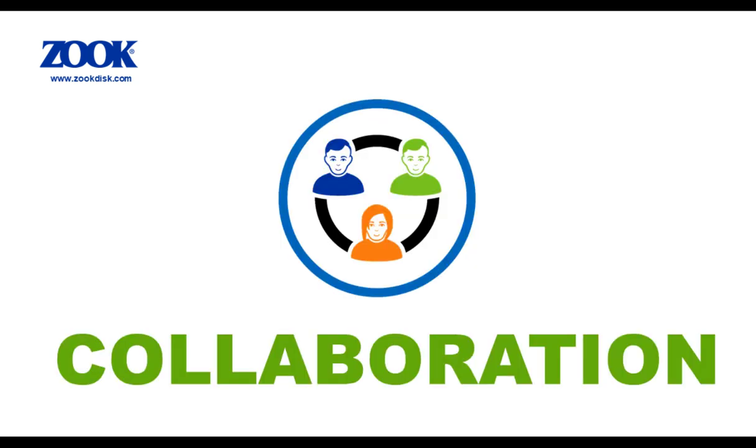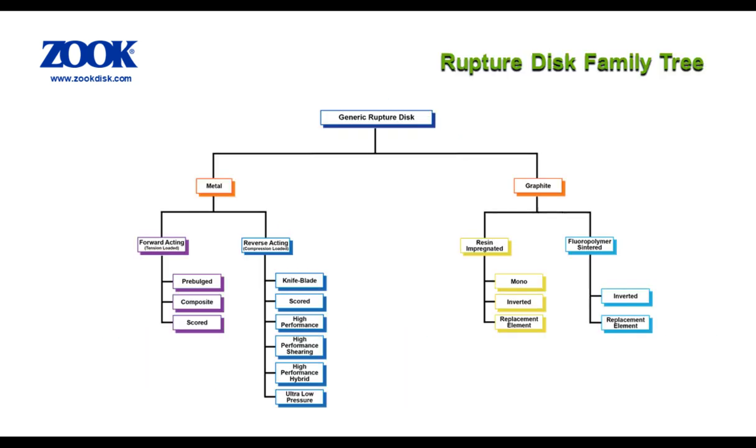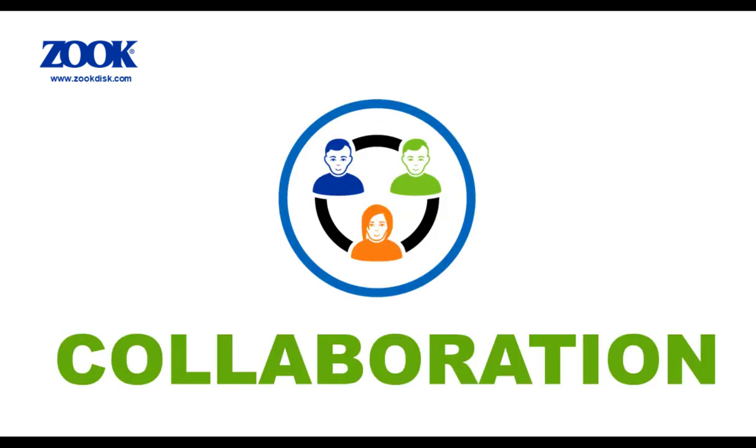Another process is a patented fluoropolymer sinter process. This involves preparing the graphite substrate to accept the fluoropolymer in both liquid and powder form. The coated graphite is then sintered at high temperatures that produces a highly bonded coating to the raw graphite, resulting in an impervious material. In addition to all resin-impregnated graphite features, the fluoropolymer sintering process has greater corrosion resistance, allows higher operating temperatures, holds FDA approval, and has a non-stick finish.